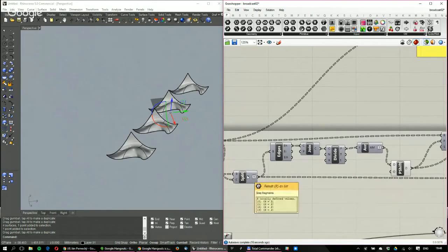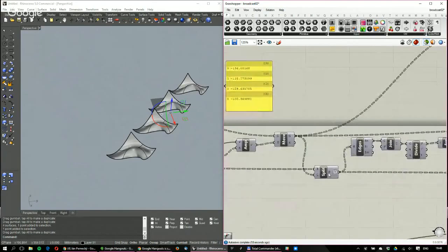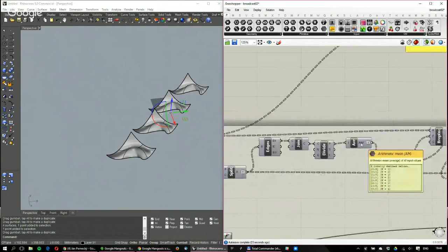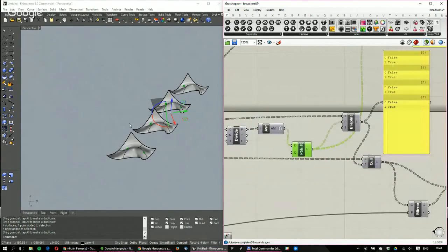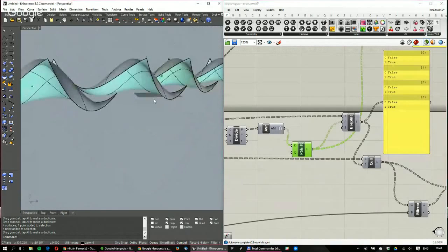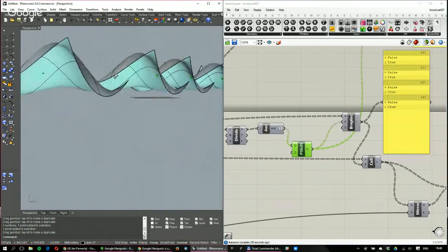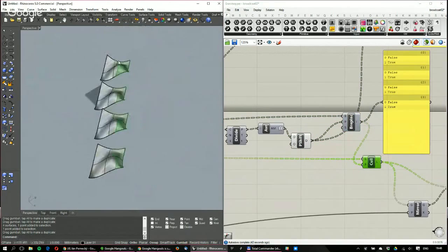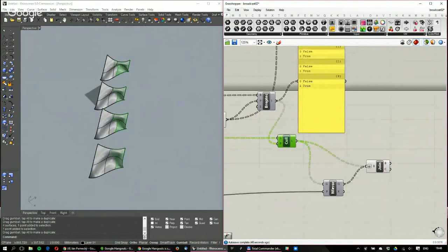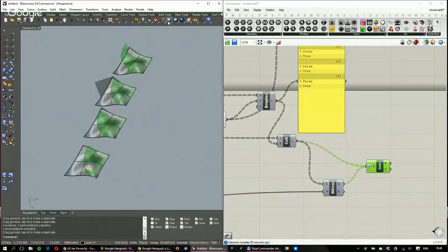For each one of these shapes, I have two subshapes here if I don't graft, but I end up having the averages grafted because the divide always grafts. So I need to shift path again to get two points inside of those, defining the central point of each of the subshapes here. Then I can cull and I will get those that I'm interested in, and then I mirror, and then I join. I end up having a perfect mirrored shape.